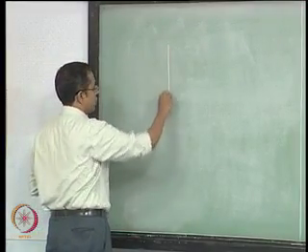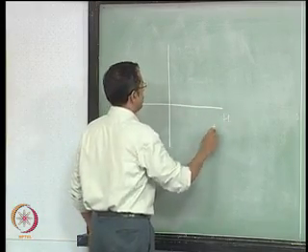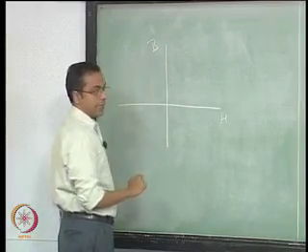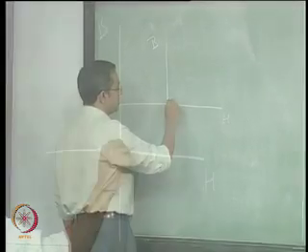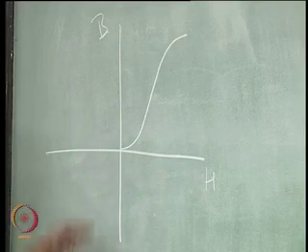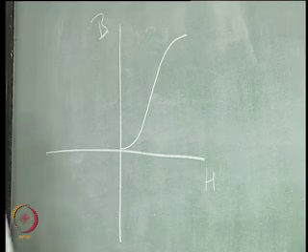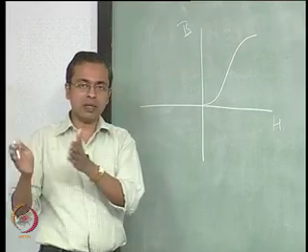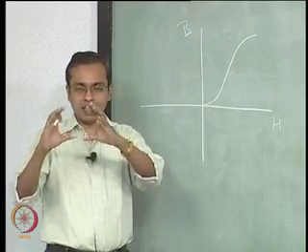Of course, this has got to do with how the magnetic materials respond to the field H. So we can draw H versus B plots, and this is for a ferromagnetic material. Okay, so for a ferromagnetic material, as you raise H, you actually see a response that looks like this. This represents the fact that within the sample, the atoms are cooperatively aligning with respect to each other, neighboring atoms, but that occurs only over a small region.